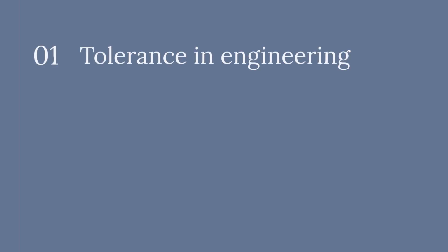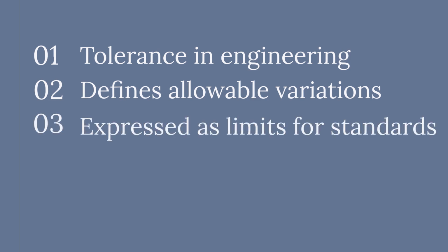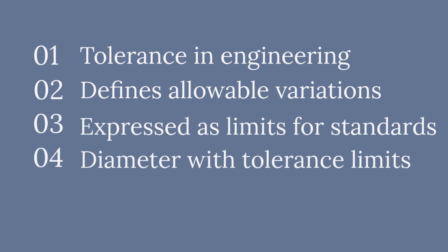In engineering, tolerance defines allowable variations. It's expressed as limits to maintain standards. For example, a diameter of 25 millimeters with a tolerance of plus or minus 0.02 millimeters. This ensures parts fit and function correctly. Tolerance is vital for quality and precision.